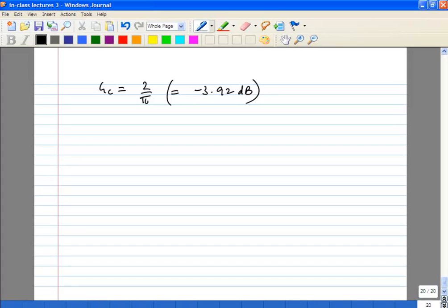Okay. So in other words, it actually has a conversion loss. But it's not a problem. As long as your noise figure is held in check, you don't mind having some loss. You can always make it up with make-up gain using LNAs. Okay.